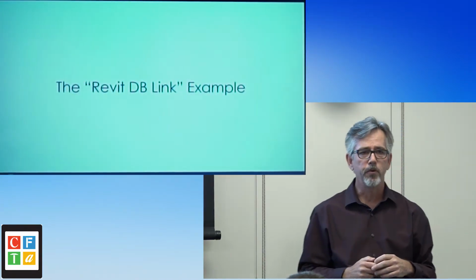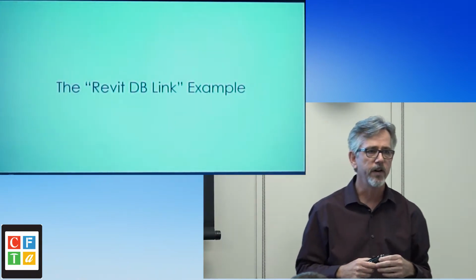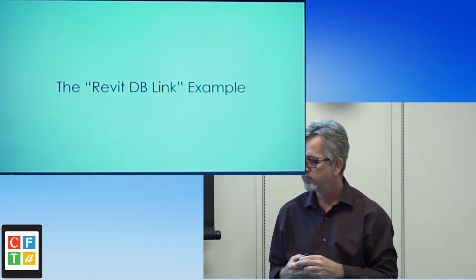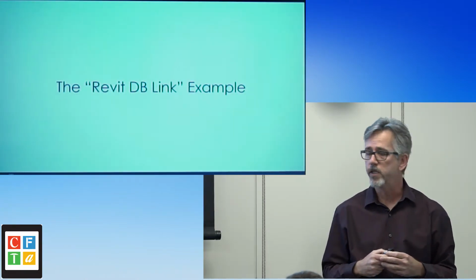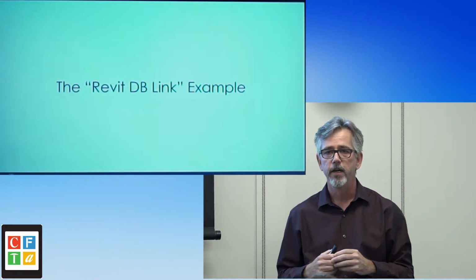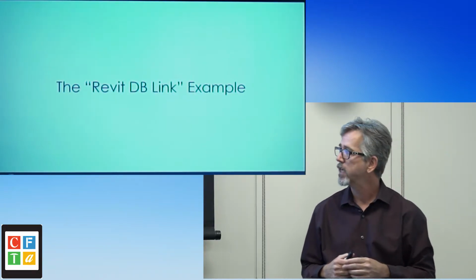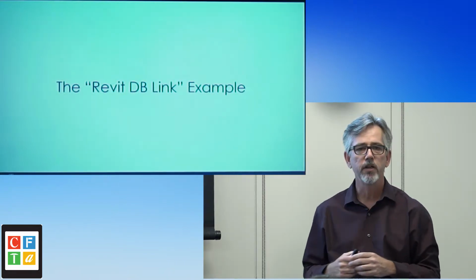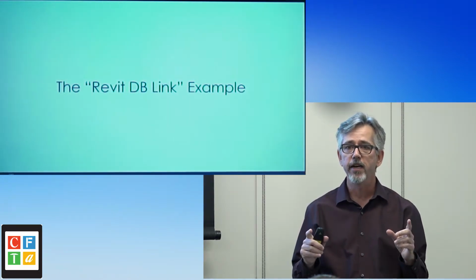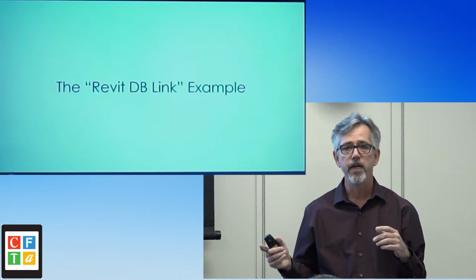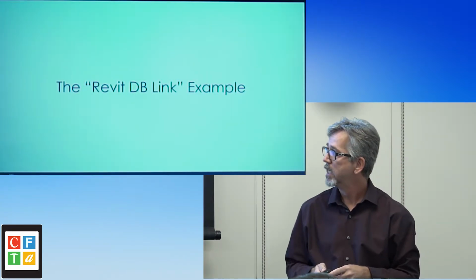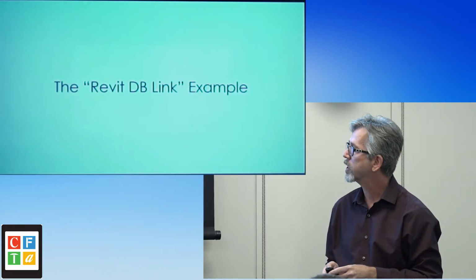There's a product that Autodesk provides. It's free if you're a subscription member. You have to be a little bit adventurous to plug this into Revit. It's called the Revit DB Link. If you've got some basic database skills, or some mad database skills, you can plug this in, and it makes it easy to extract the data in and out of a Revit model to a database. I use Microsoft Access as an example because most people have it, and it's pretty simple to understand.